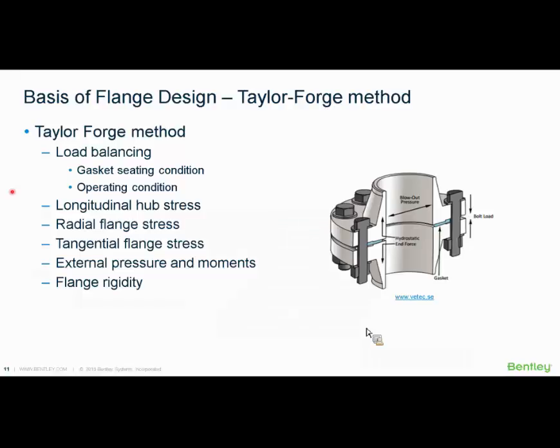ASME flange design also provides criteria for longitudinal hub stress, radial flange stress, tangential flange stress, and also allows for taking into account external pressure, forces, and moments. And there is also a check for the flange rigidity, introduced into the newer versions of the ASME flange design.